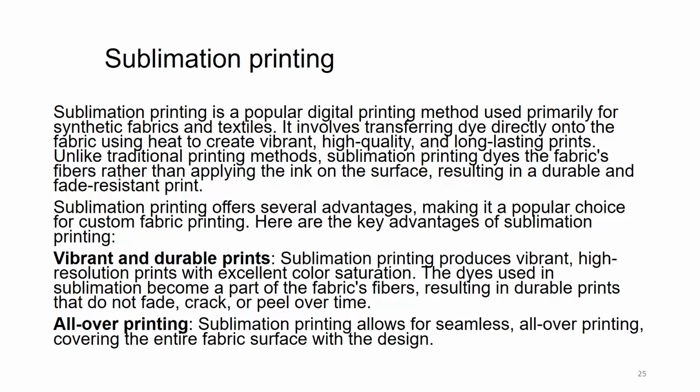Sublimation printing offers several advantages, making it a popular choice for custom fabric printing. Here are the key advantages of sublimation printing. They are vibrant and durable prints. Sublimation printing produces vibrant, high resolution prints with excellent color saturation.